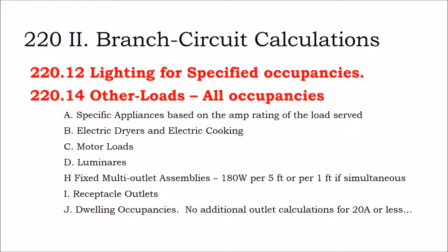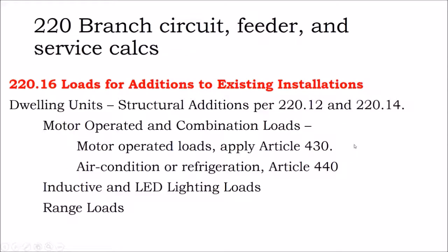So especially for your perhaps non-continuous loads like dryers and range stoves, or commonly found loads like lighting loads or receptacle loads, have different rules, as well as separate rules for dwelling units versus non-dwelling units. Like a home where people are living full time is subject to more stringent regulation than, say, a warehouse.